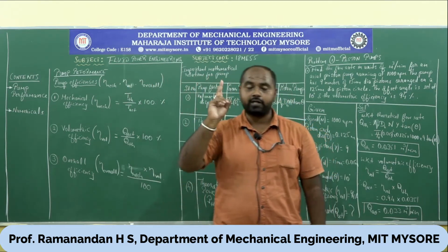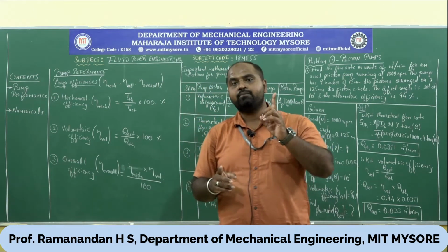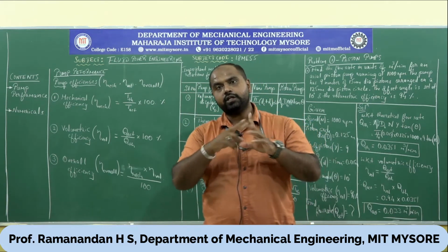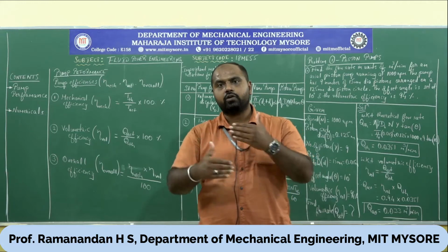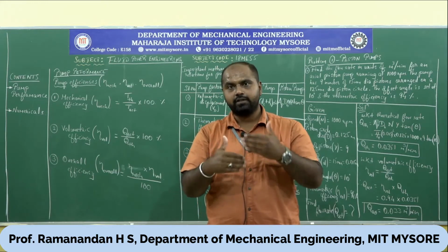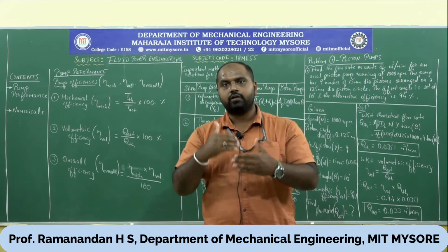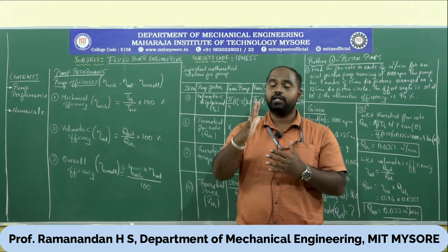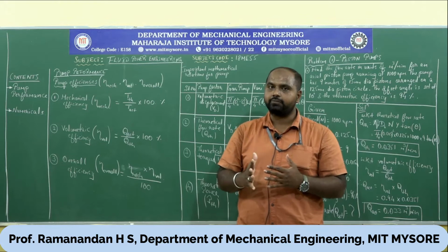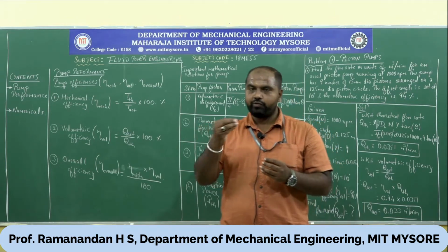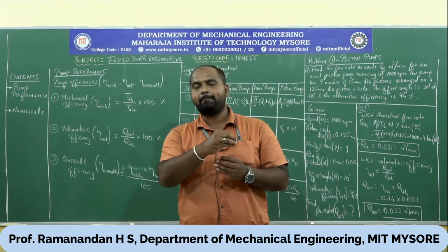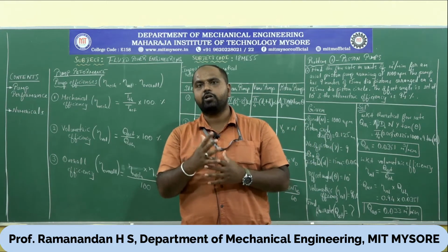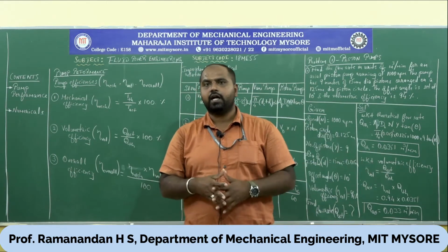So second important efficiency. First one is torque, because of the rotational aspects of the shaft. The number of rotations of the shaft developed because of the fluid energy gives the mechanical efficiency aspect. The amount of fluid discharged by the pump directly contributes to the volumetric efficiency aspect.